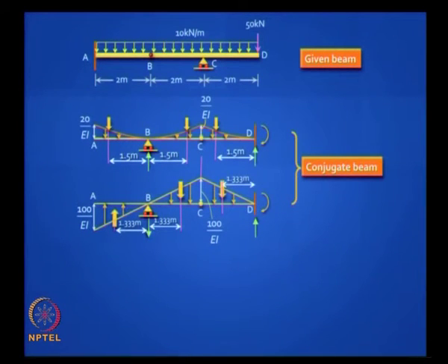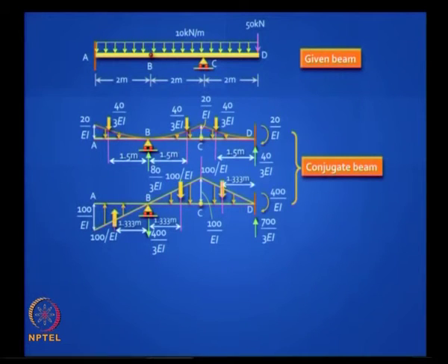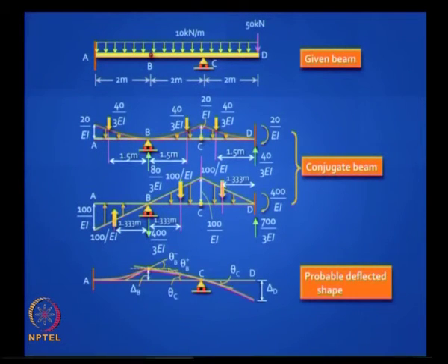In the conjugate beam, the boundary conditions are as shown. Now instead of putting on that beam that big complicated diagram, it is good to separate out the curved parts from the straight line parts, just for simplicity in calculation. If you do that and you do superposition, you can actually find out the centroids of the resultant forces and analyze it. Look carefully at the values that you need to compute, because at B you will get two values of slope, because the slope on the left side and the right side are not going to be equal. That is because you have a discontinuity in the shear force diagram in the conjugate beam, because you have a support there. So you can calculate all these very accurately.